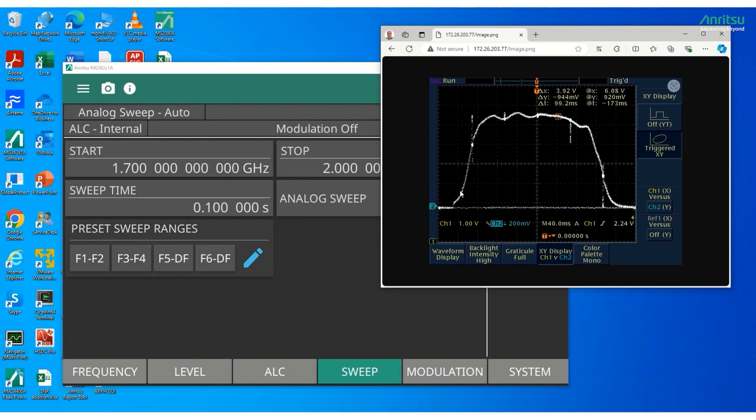So if you look at the RF detector specifications, the RF detector gives you a few millivolts, like 5 millivolts, at minus 30 dBm, when the RF input to it is minus 30, and it gives you nearly 1 volt output with a peak of plus 13 or plus 15 dBm. So it's plus 15 and minus 30, so you're getting a dynamic range of almost 45 dB with this setup.